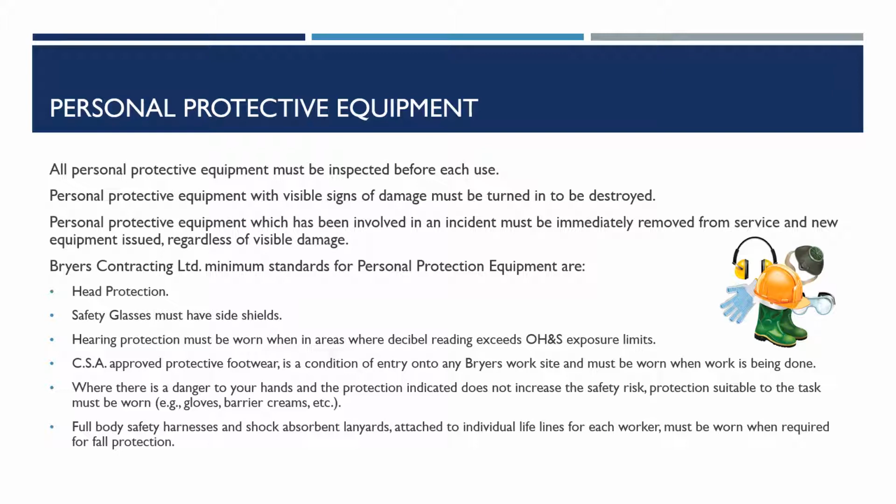CSA approved protective footwear is a condition of entry onto any Bryers worksite and must be worn when work is being done. When there is a danger to your hands and the protection indicated does not increase the safety risk, protection suitable to the task must be worn. Full body safety harness and shock absorber lanyards attached to individual lifelines for each worker must be worn when required for fall protection.